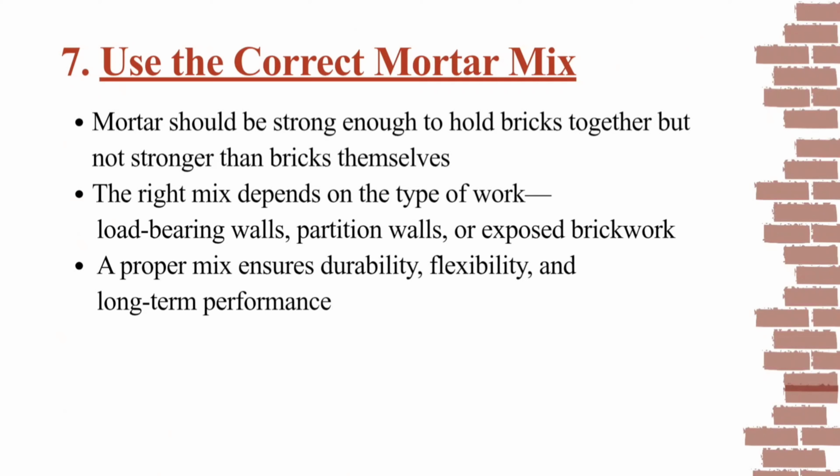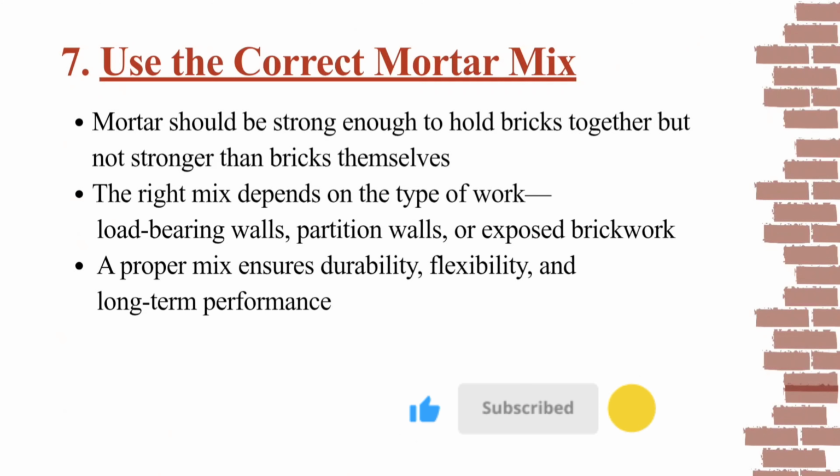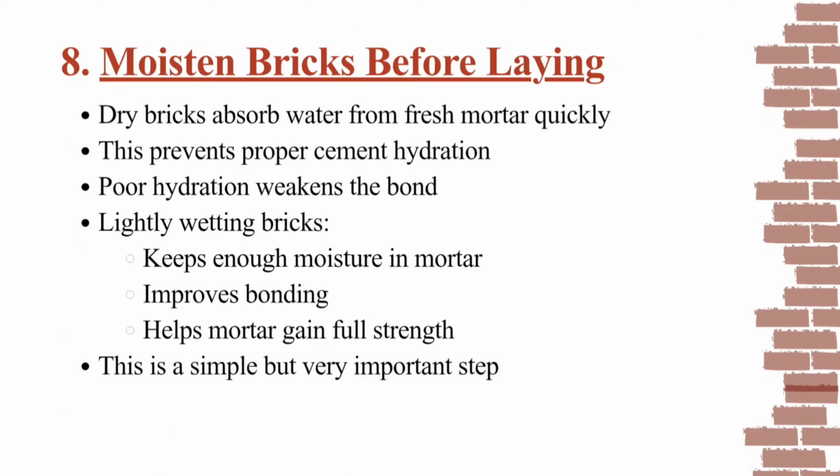And that's why the use of a correct mix is an important thing. The right mix depends on the type of work, like load bearing walls, partition walls, or exposed brick walls. A proper mix ensures durability, flexibility, and long term performance. So this is also an important point in brick masonry work.